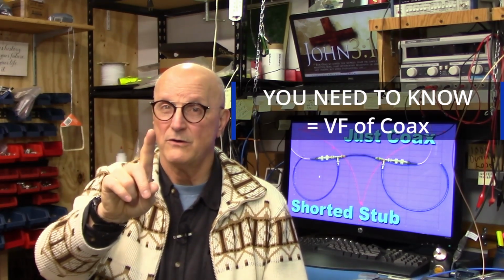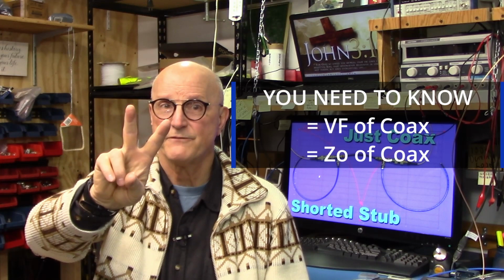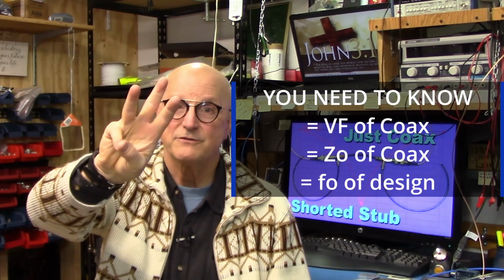With this said, remember that a Smith chart assumes ideal components. The feed lines are lossless, and the capacitors and inductors are ideal with no parasitic inductance or capacitance or resistance or any of that. The best we can do is plan for having to make adjustments to our design. Okay, back to the design itself. There are two ways that we can approach this design. In either event, you will need to know the velocity factor of your coax, the characteristic impedance of your coax, and the frequency of interest of the filter.